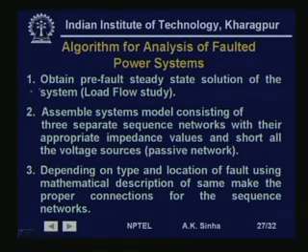That is, we had seen that a fault acts as a structural change, that is, the inclusion of an impedance, the fault impedance, into the system, and this we can simulate by using Thevenin's theorem, that is by putting the impedance at the fault point in series with a voltage which is opposite to the open circuit voltage at the fault point. So, that is what we do in this case.